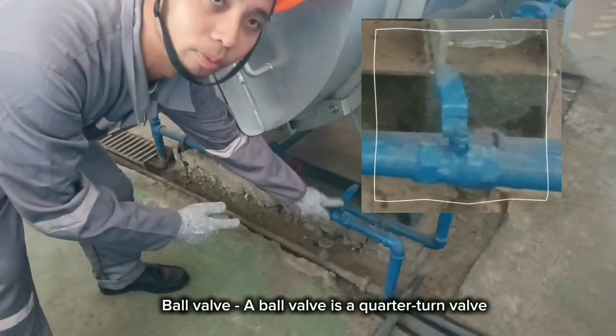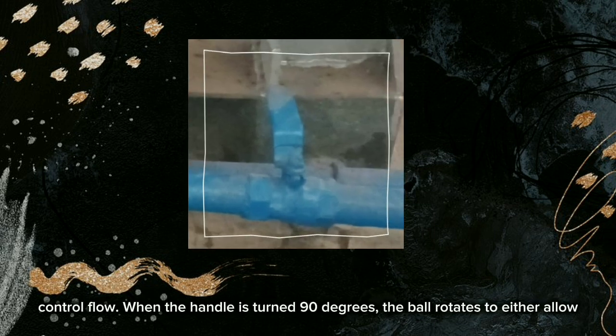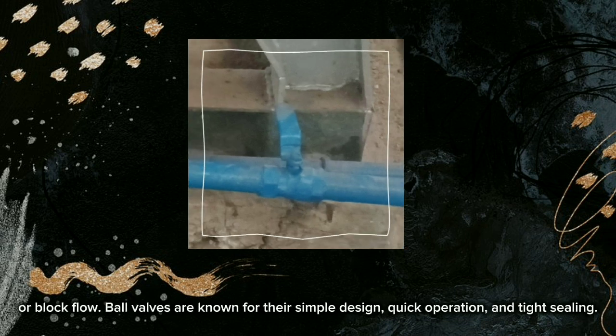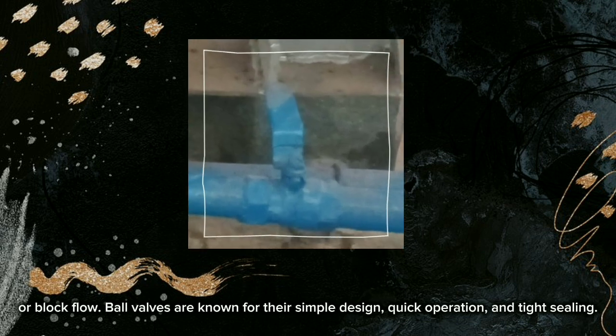Ball valve. A ball valve is a quarter-turn valve that uses a spherical disc, a ball with a hole bored through the middle, to control flow. When the handle is turned 90 degrees, the ball rotates to either allow or block flow. Ball valves are known for their simple design, quick operation, and tight sealing.